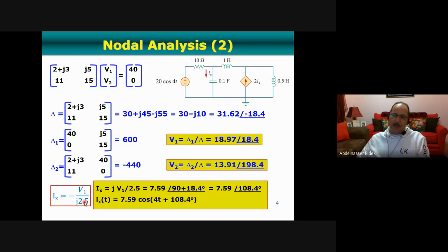Okay, so what is this actually? It is 2.5 in amplitude, and the angle is 90. And if you have a negative in the bottom here in the denominator, you can add 180 degrees. So you can say, okay, this one is negative. It is 180 degrees plus 90 because of J, which will be 270, or it is negative 90.